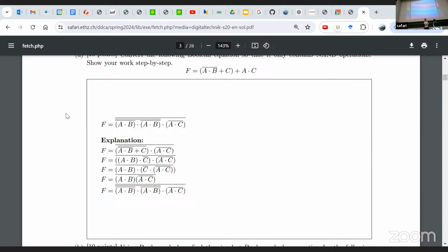For example, it could come up with something like this. You draw a diagram, you write the gates and things like that, and they ask you, okay, how fast can you run this as a pipeline stage? Well, then you have to think, okay, I need this gate to complete, this gate to complete, this gate to complete. I also need the setup time of the register. From that, you get a cycle time. One over that is the frequency. And you say, hey, this thing will run at a gigahertz.